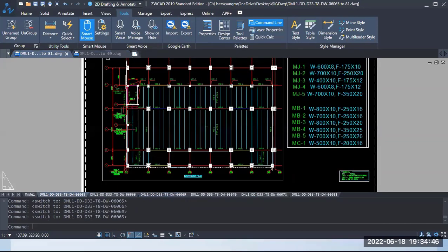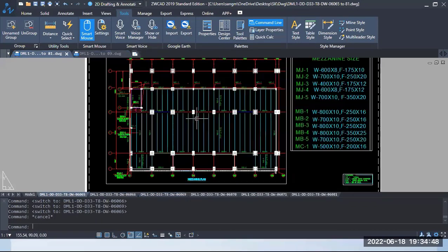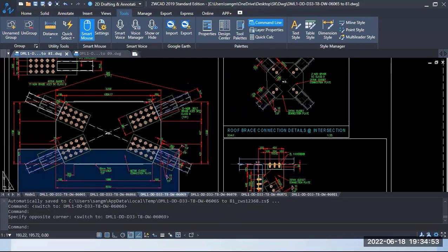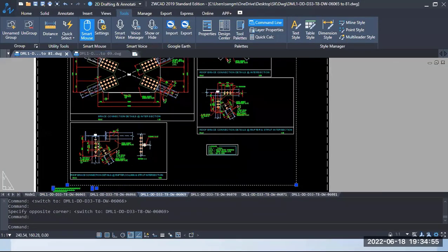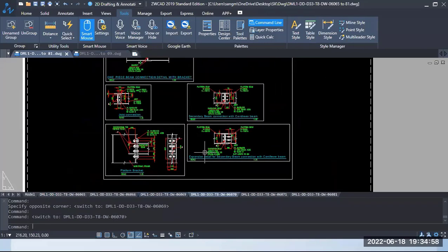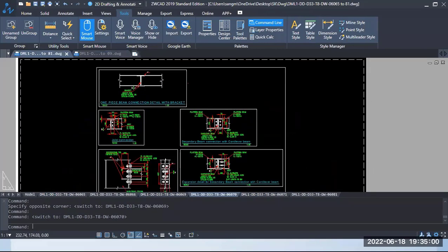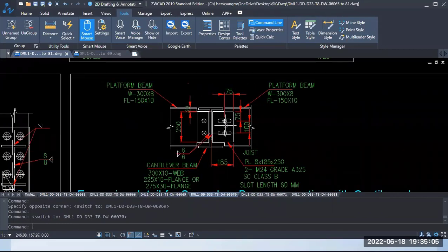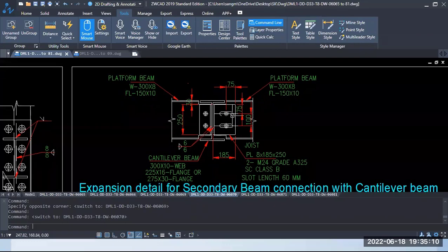We have discussed the bracings as well. We have discussed the mezzanine connections. I think we have discussed the top bracing, roof bracing. And this is one example of slotted connections at the location of the expansion joints. We have provided slot connections here, so no forces will be transferred. It isolates the structures. As I told you, we have a lot of expansion joints.